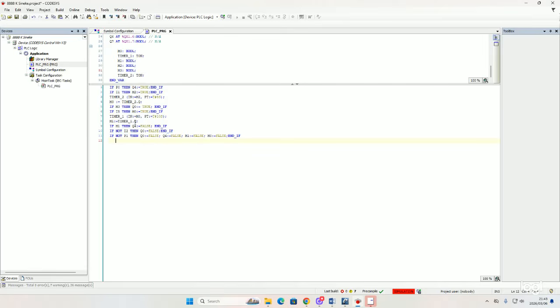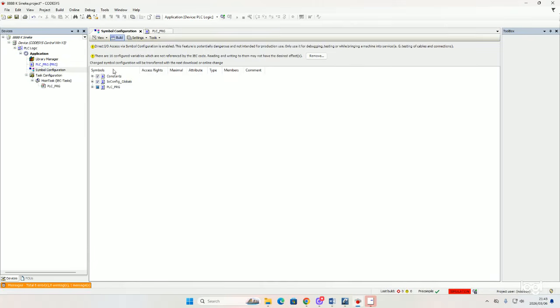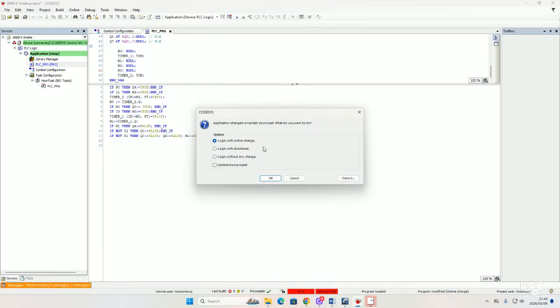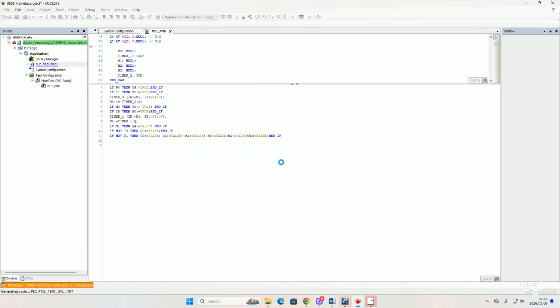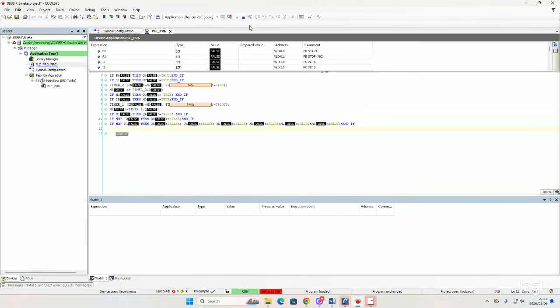Okay, let us just observe the rest. We forgot, because since we introduced a new timer, we need to insert our M2 equals false, M3 equals false. Then don't forget to end your code. Great, so from here, build, enable your code, PLC, log in, we download, don't forget to play.